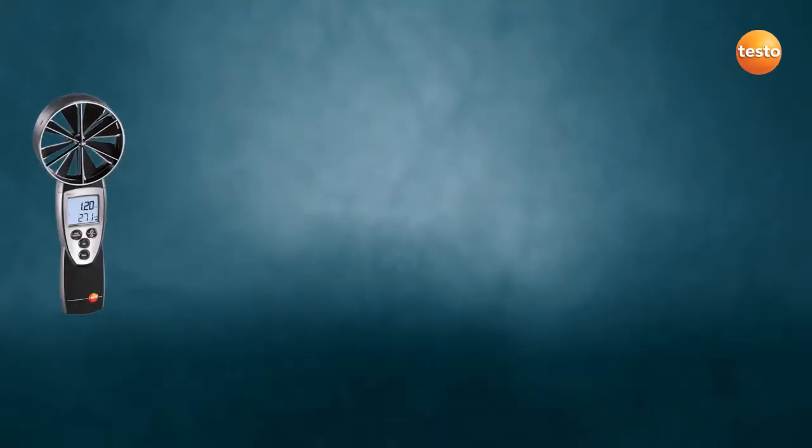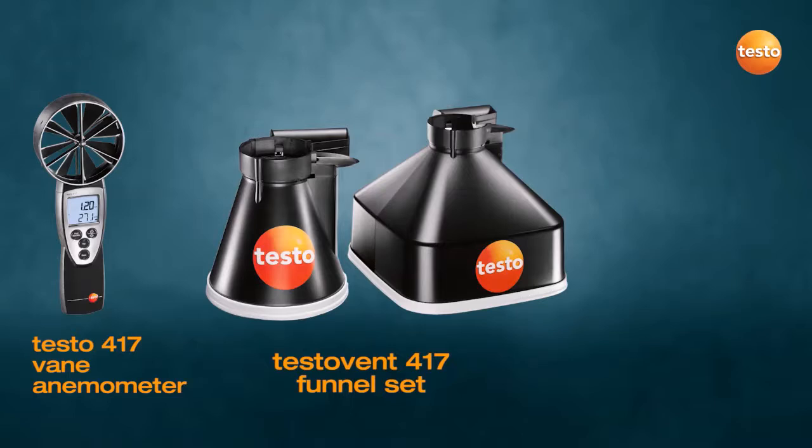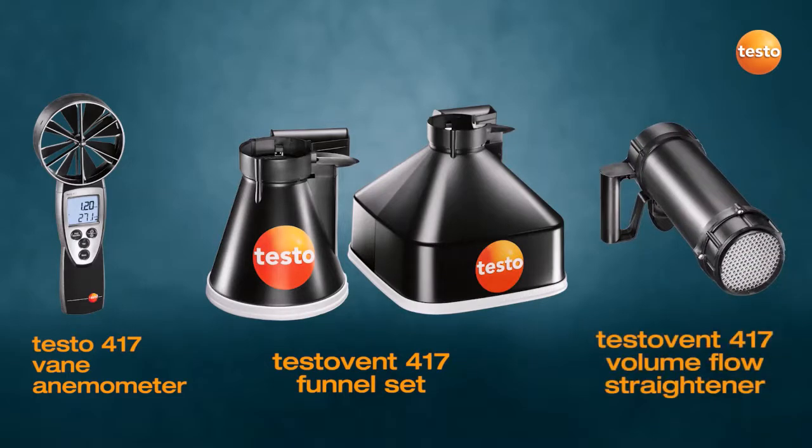You will be perfectly equipped for taking measurements at supply air and exhaust air outlets of a room ventilation system with the Testo 417 Vane Anemometer. It can be combined with two funnels, allowing volume flow measurement at grills and diffusers, and thanks to the Testo Vent 417 volume flow straightener, it is also suitable for swirl outlets.